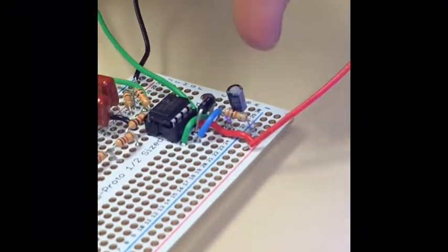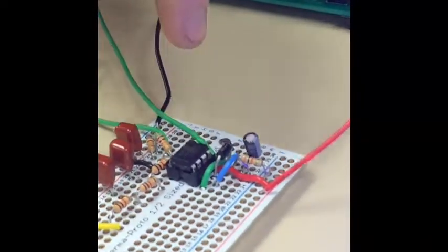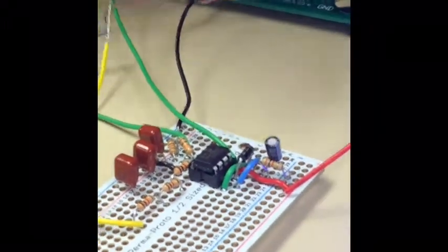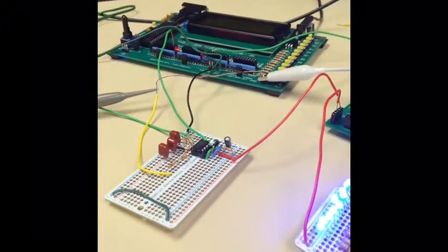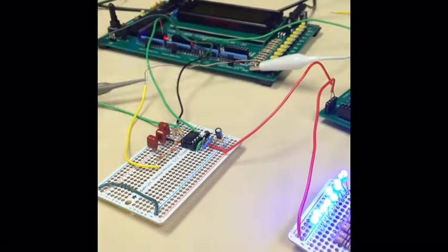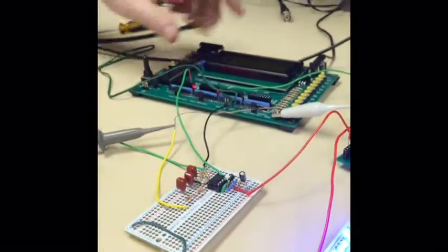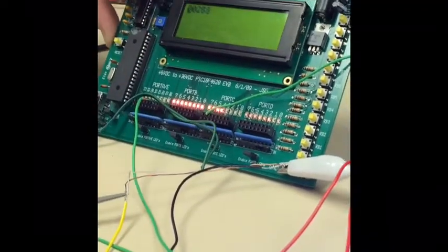And what this does is charges the capacitor through this diode, and then when the op amp goes low on the lower portions of the wave, the diode cuts it off so it can't go to ground, and it just discharges through this resistor. So you get a charging, and then you get a little bit of ripple out. So it takes our half wave rectified signal and equates that to a DC analog voltage. This is the output from that, and it's connected to pin A1 of our A to D read PIC here.